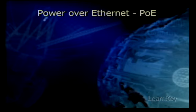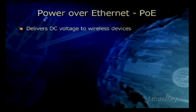Power over Ethernet is a method of delivering DC voltage to an access point, a wireless bridge, or a wireless workgroup bridge over the Cat5 Ethernet cable for the purposes of powering the unit. Now, in our context, that's what it's limited to, but in the industry, we are seeing power over Ethernet being used to deliver power to a lot of other devices too, such as IP phones.